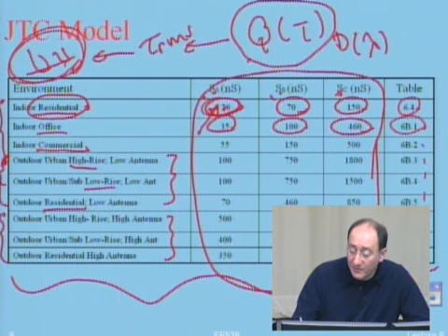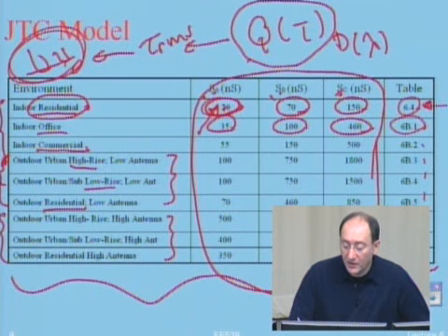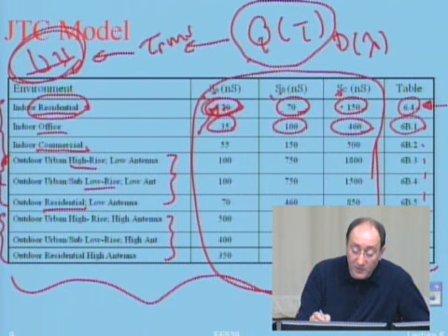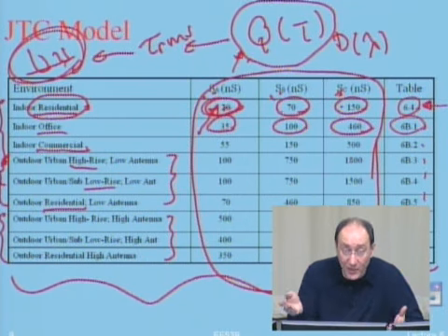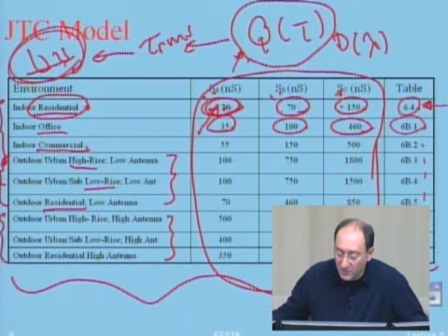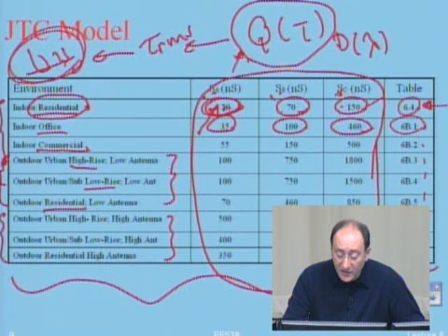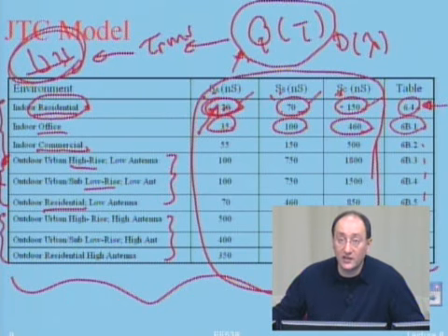Now you get one example, which is the one that was my example in the book. You have three delayed Q sub taus, which are impulse response squared, delay power spectrums. One of them has an RMS value of 150, the other 70, the other 20.